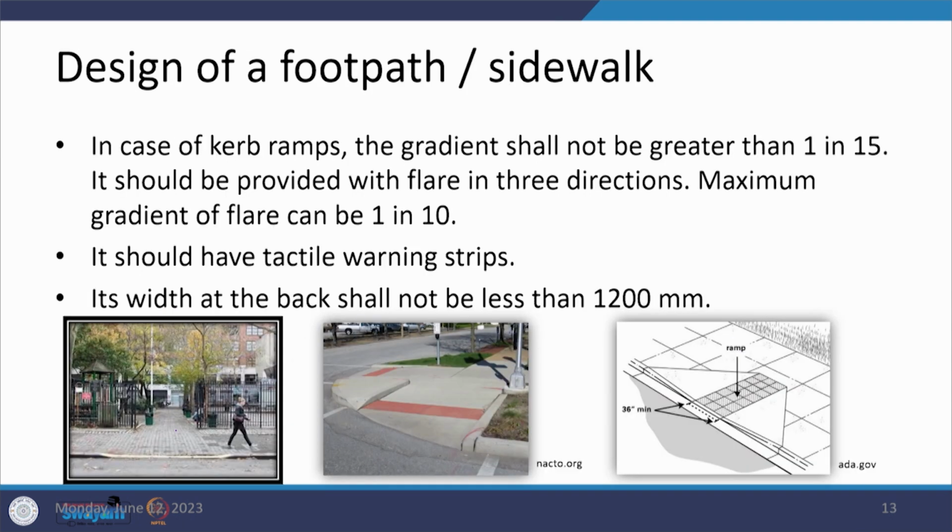for the multi utility zone or MUZ. Now, in continuation of the width and the height which we have talked about, what we are talking about here is the connectivity of the footpath with the carriageway. Say in this case you can see that there is a footpath here and there is a carriageway being provided on this side. So, there is a width which is 150 mm. Now, the people who have certain restrictions in their movement may find it difficult to come down 150 mm, and therefore we should provide a ramp, and that is the way the facilitation of the movement should be taken care of.